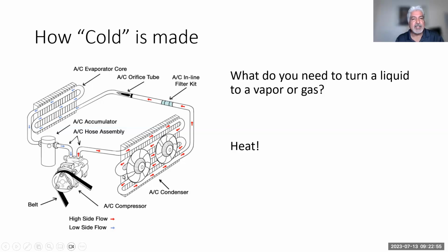In this case, we've got airflow going in here. We've got the evaporator right there. We mentioned in part one about any contamination or dirt, and that cabin air filters can also be clogged. But what I'm trying to show you here is that this is using an orifice tube system, unlike the thermostatic expansion valve. So the name itself is telling you there's an orifice there. That orifice is creating a restriction. So therefore the compressor is pushing.